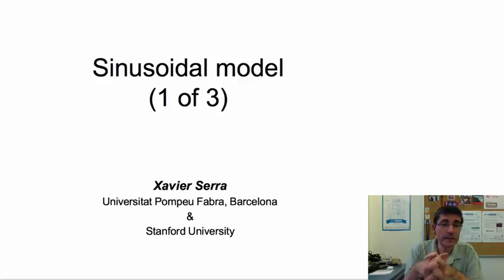And that's all for this lecture. We have presented the sinusoidal model, a sound representation that can be built on top of the short-time Fourier transform and that can reduce the amount of spectral information to be considered. However, to use it, we have to understand a bit about spectra and about windows. Hopefully, you understood some of that in this lecture. Now we have to complete the explanation of how to identify the spectral peaks and how to synthesize them. So this will be covered in the next two theory lectures.